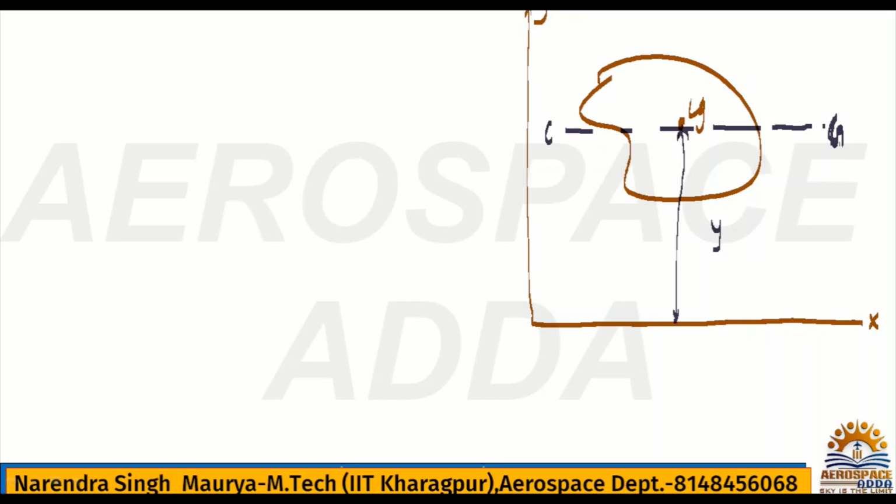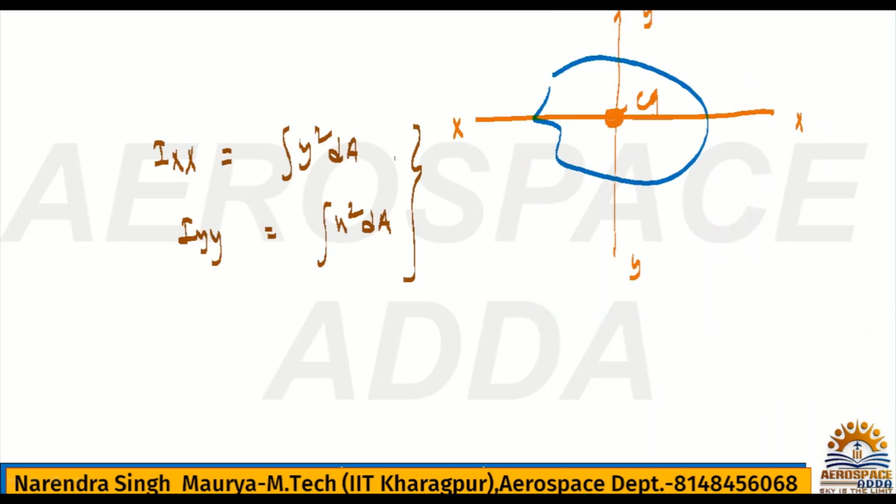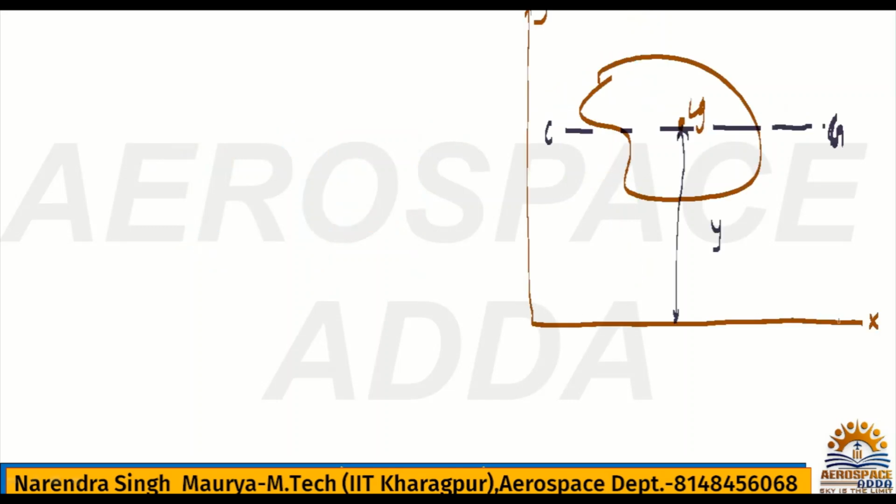Now I want to calculate Ixx. So how to calculate the moment of inertia Ixx for this particular body? I told you Ixx you can directly write as the integral of y square dA, which is the second moment of area. But this is possible only when the axis is passing through the CG of the body. But here, this axis is not passing through the CG. This x axis is away from CG by a distance y. Then how to calculate Ixx? For that we have a theorem called the parallel axis theorem.